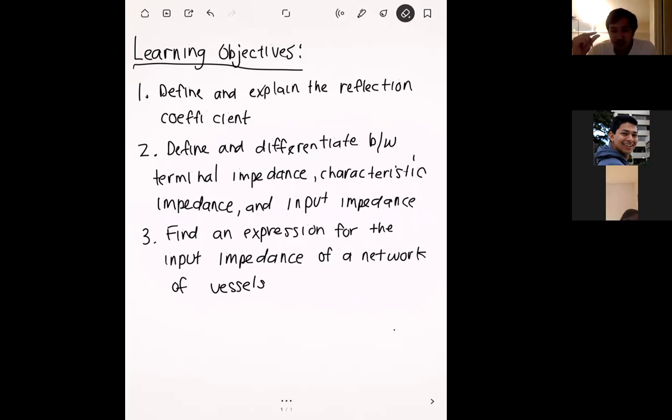Hexes can be squished really well, but they can't really be stretched all that much. If a hex has to do some weird stuff, that's going to cause a lot of issues with your simulation, whereas a tetrahedral mesh might be able to do it a little bit smoother, where the elements aren't as distorted.